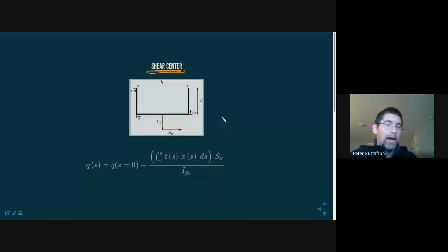But what I can describe for you is, we describe stall as being a singular event, like it stalls or it doesn't. And real pilots sitting in cockpits, different airplanes stall very differently. Some have a soft stall, some have a very sharp, hard stall. And it does depend a little bit on how the aircraft is loaded and what your flight condition is at that moment.